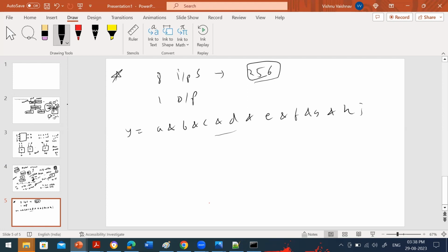Let me take a side example to explain this, a small example understandable for all. Let's say you are verifying a chip that belongs to a mobile. There are three highlighted features: call, SMS, and music play. Your responsibility is to verify the call, SMS and music player features. First, take call. You will read the specification carefully. You will try to understand what this feature says, what all the inputs of call are, what all the outputs of call are, and what the exact functionality is.